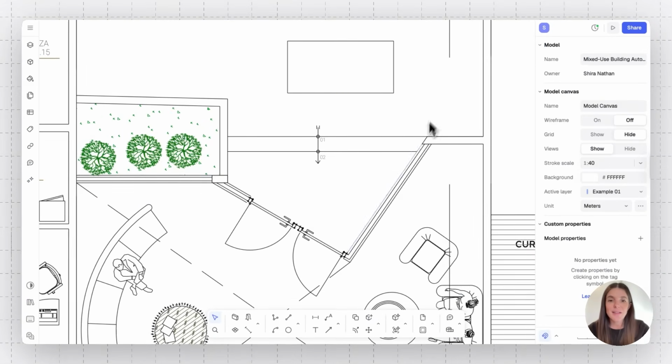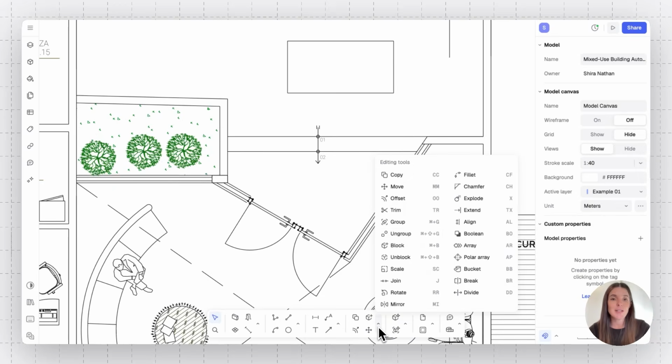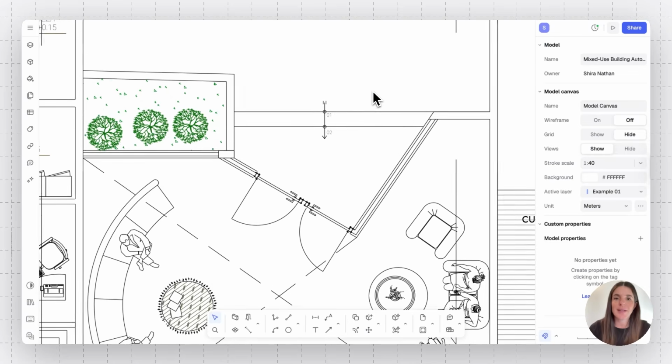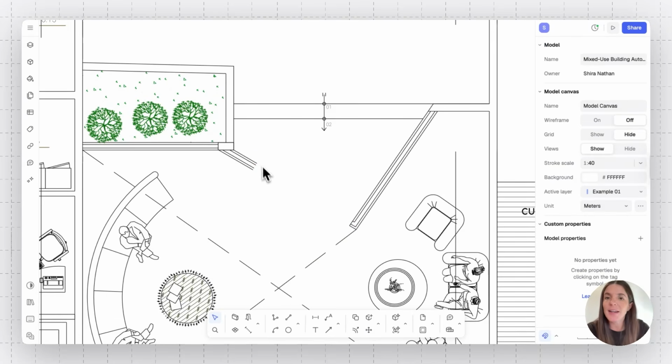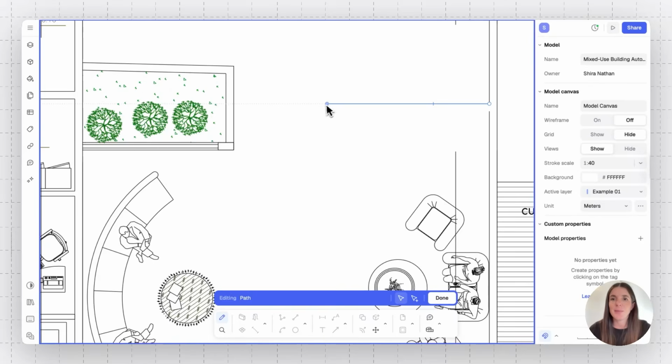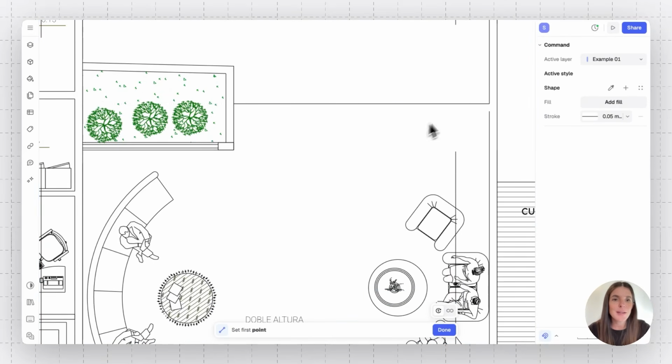And then when you're ready to edit these, you can use the classic CAD commands, which will apply on the vector lines, like offset, trim, array, divide, break, and so on and so forth. So one of the options you have in your file is to just quickly dive in there and start redesigning and editing it, deleting the vector lines that you have in place. Select these for now too. And then you can either build upon the lines that you have, let's say this one, or grab new lines or offset them and so on and so forth.